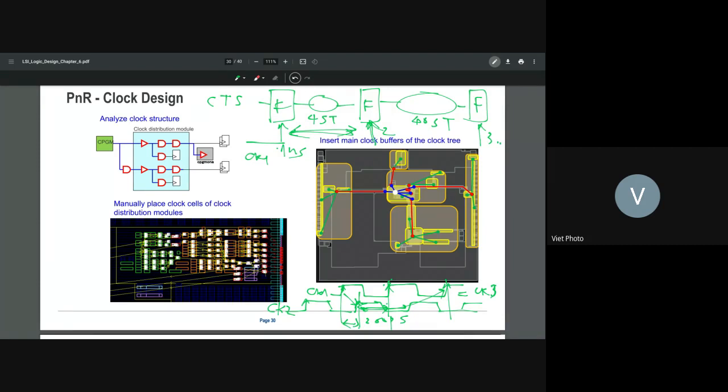So that means there are two steps. One step is to balance the clock. The second step is what they call useful skew. You remember when we have clock skew that is not on purpose, that we don't want, we just call that clock skew because it's harmful, right? Let's say that instead of skewing earlier, it's skewed later. When it's skewed later, it will eat into the period of the next stage. That hurts, right? So we don't want that.